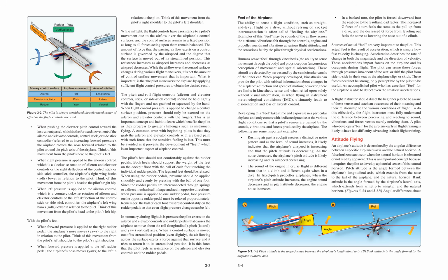The sound of the engine in cruise flight is different from that in a climb and different again when in a dive. In fixed-pitch propeller airplanes, when the airplane's pitch attitude increases, the engine sound decreases, and as pitch attitude decreases, the engine noise increases.